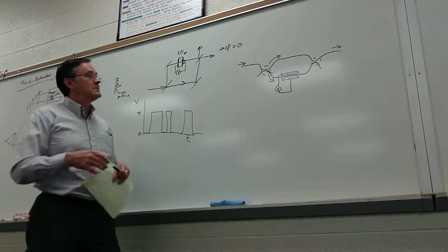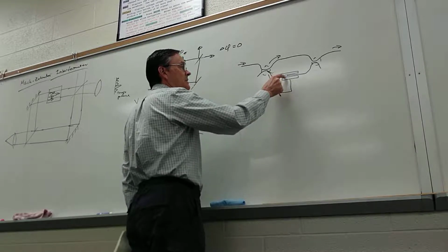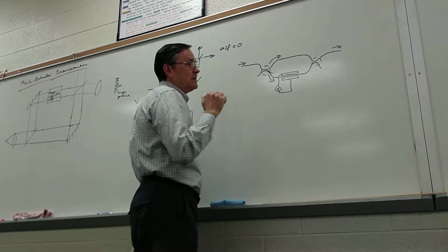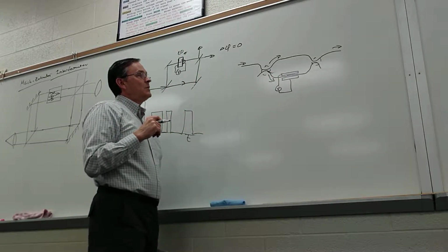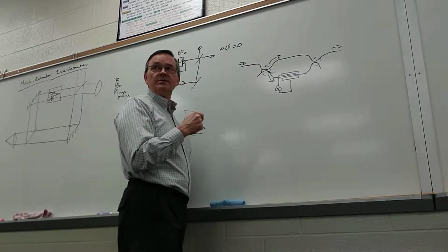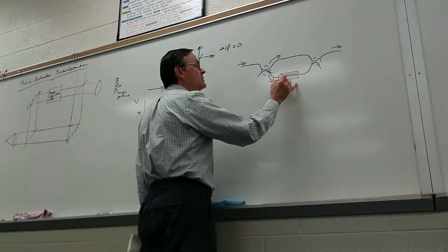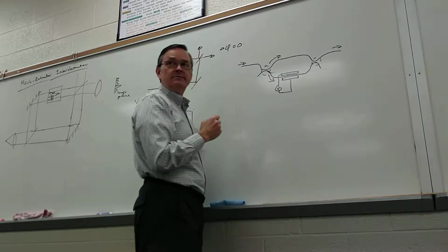And in fact, what you end up doing is the electrical leads that you connect to the electrodes, because you want to modulate so fast, you have to worry about propagation time of your voltage from one end of the lead to the other.